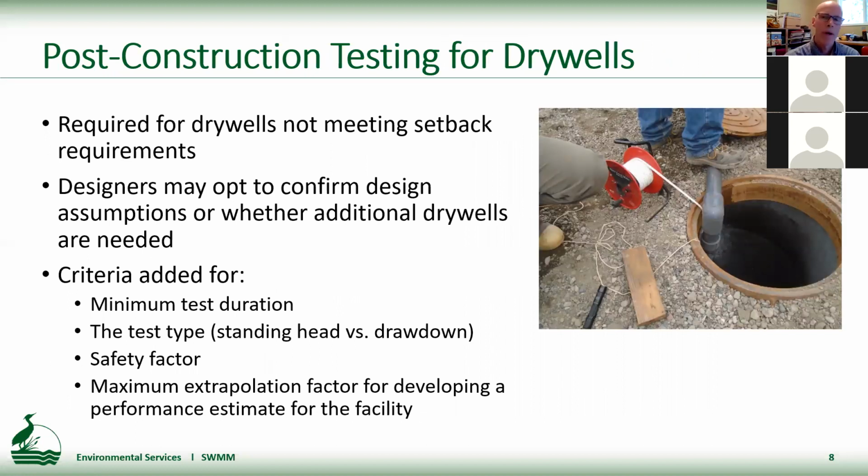Pre-construction testing for drywells. There's new language about that in the SWMM. So this is required not just for drywells under buildings, but any drywells not meeting the structural setback requirements. Designers may opt to do this voluntarily to confirm design assumptions or whether additional drywells are needed. Say the design calls for 3 drywells, but after installing the first one, a test can be done that indicates really 2 are required.